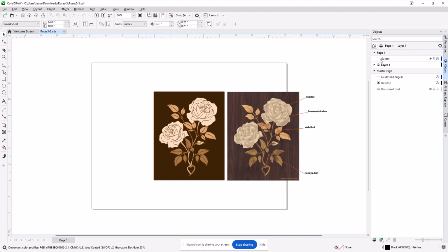When you import a picture from somebody else, if you're lucky, everything's in good layers, and Vincent does pretty good work that way. What's of interest in here is you'll notice that I've got SVG data. These two first items on objects are associated with the SVG format and are not needed for working in CorelDRAW in this environment. Everything is currently locked, meaning you can't do anything anyway. I can't really select or work with any of these pictures or objects until I undo them.